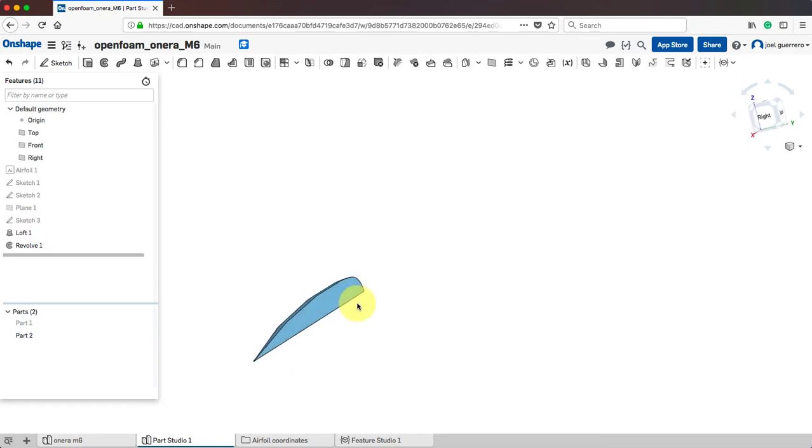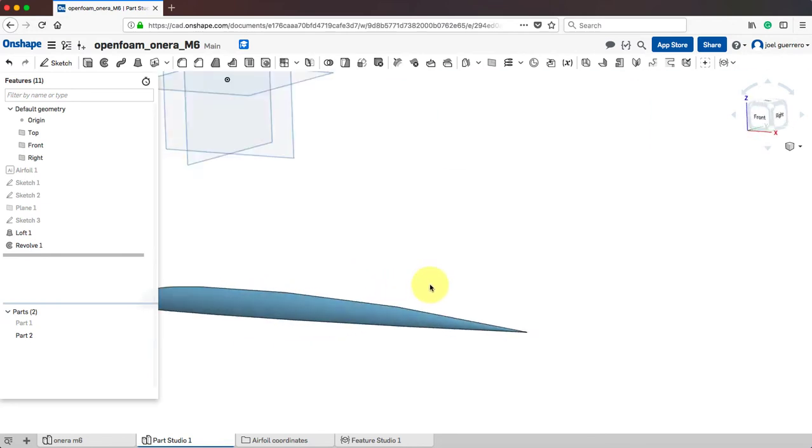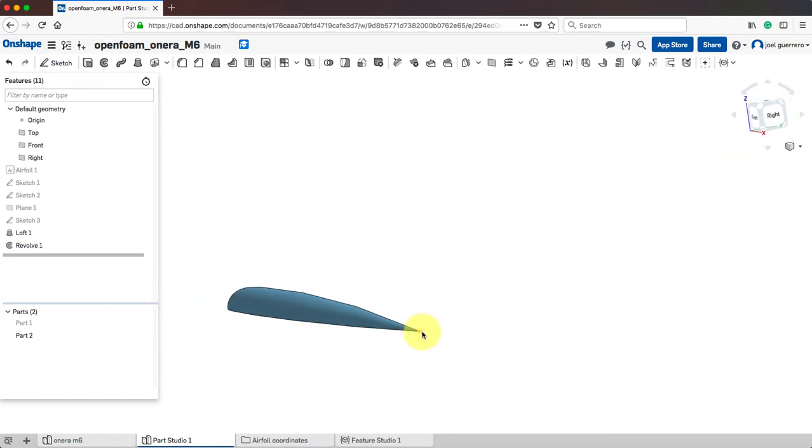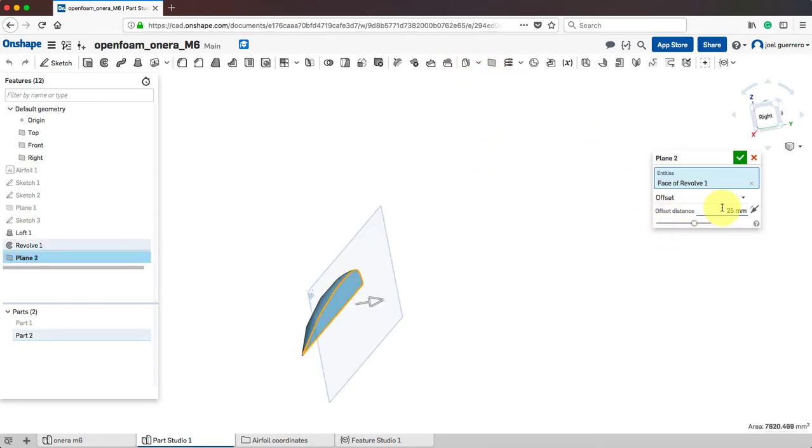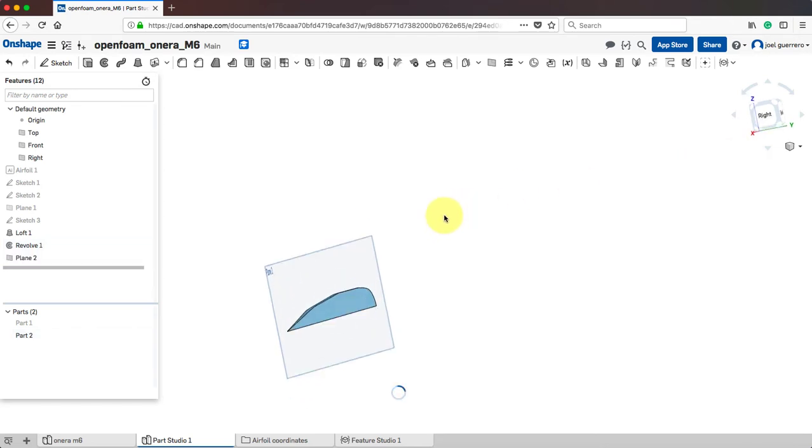What I would like to do is create a plane in this face, project this curve and this curve in the respective planes, then split those lines, and then create a cross section of this part. That is the one I will use to loft from the cross section to these points, following these guidelines. So the first thing is to create a plane in this face. You click here, and I will choose 0 offset, so I'm perfectly in that face.